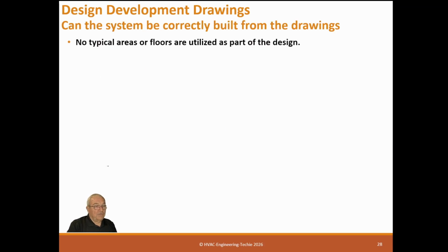No typicals. Here I'll go through my list, and I'll explain why. No typical areas or floors are utilized as part of the design. This, I understand, may save you a little bit of drawing time, but in the age of AutoCAD, it should not matter. If the architect does typical floor plans, shame on him. But trying to deal with typical floor plans later on in the construction process is a nightmare.